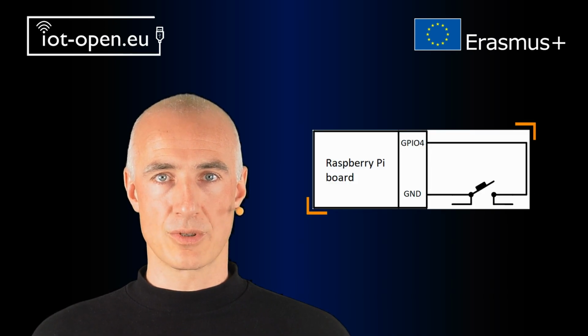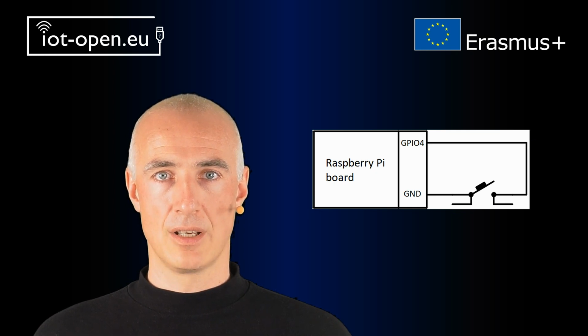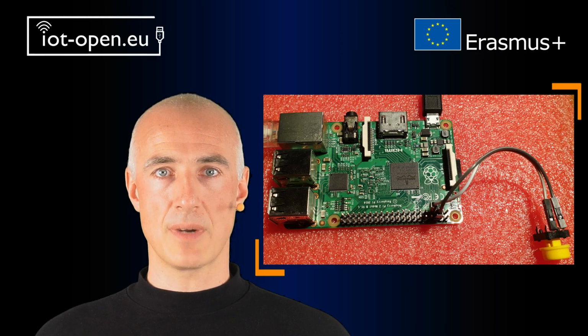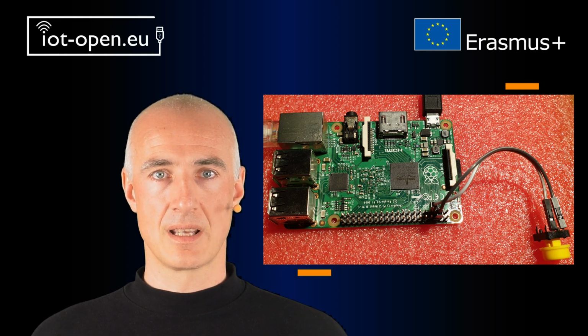The most common use of a push button is as an input device. Both solutions can be used as simple object detectors, or as AND switches in industrial devices. Here we present a solution where a push button is connected to GPIO4. To work properly, GPIO4 must be configured as a digital input. Pressing the push button connects the GPIO4 pin to the board mass.